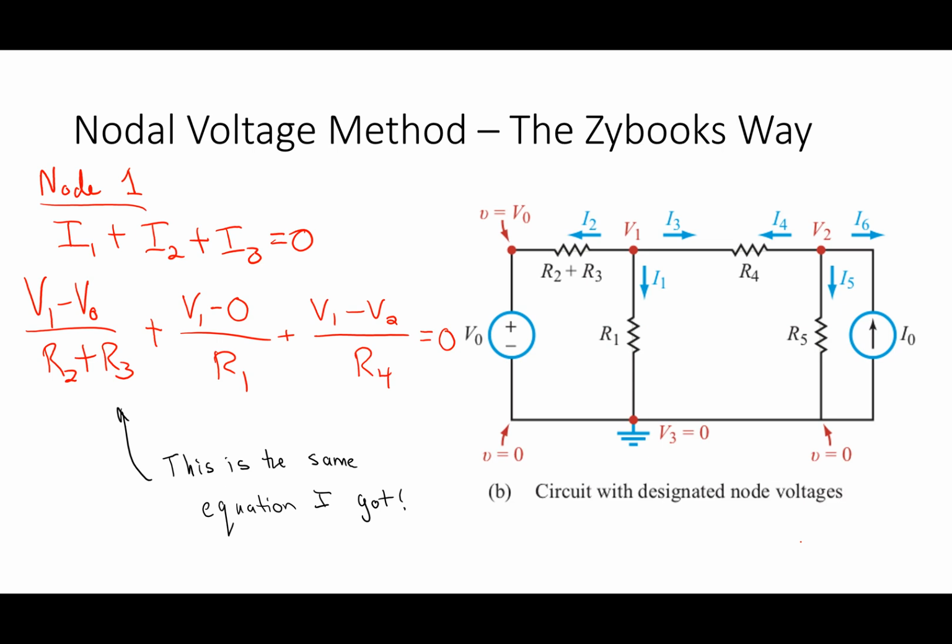What they then do is say, looking at this, all of my currents are going out. So I sum all those together, out equals in. Nothing's going into node one. So I put I1 plus I2 plus I3 all equal to 0. All right, you guys follow that? Okay. So when I look at that particular equation, all right, what they then do is they say, okay, well, I1,